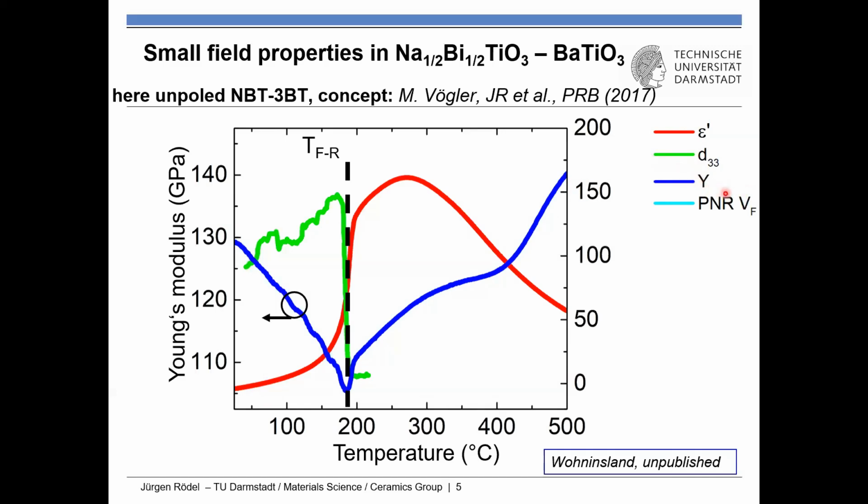If we measure to 800, I didn't plot it for you, we will find it. So at the ferroelectric relaxor transition, it's very soft. This is actually a sharper determination of the transition temperature than permittivity or piezoelectric coefficient. At least I think so.